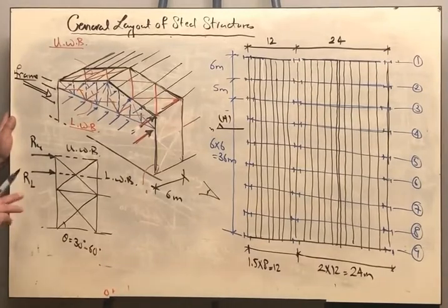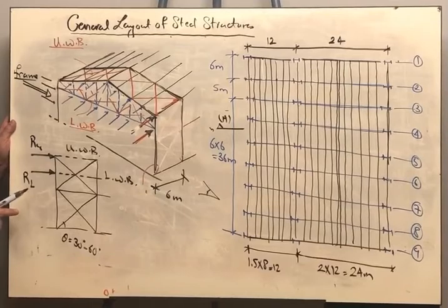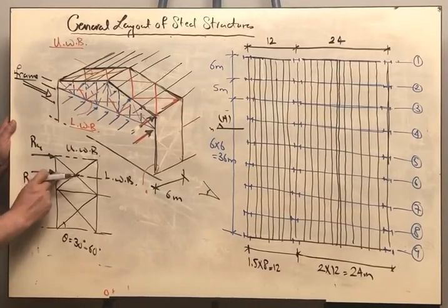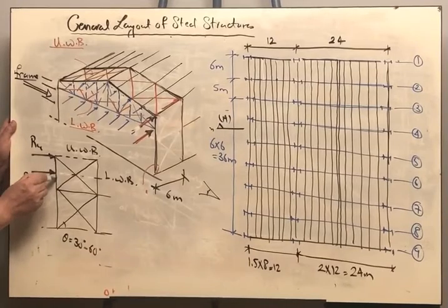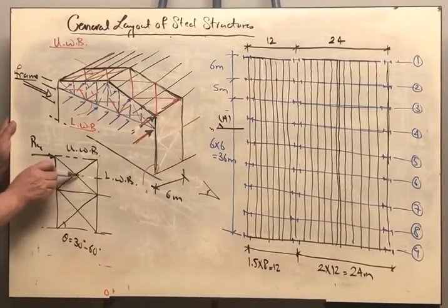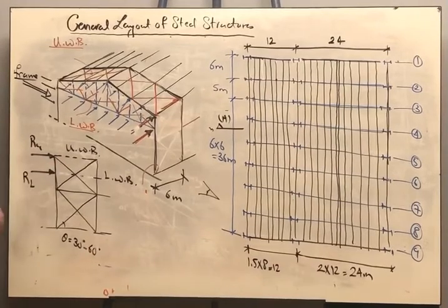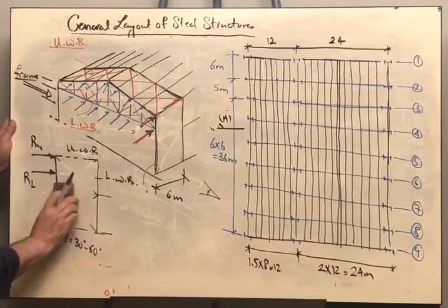Now, such an answer means that he or she did not study with me 302. Because in the trusses, you cannot have a force applied in the middle of a member. Whenever you are having a force here, we should have also a member in the transversal wind bracing. This should not be possible. I should not do that.